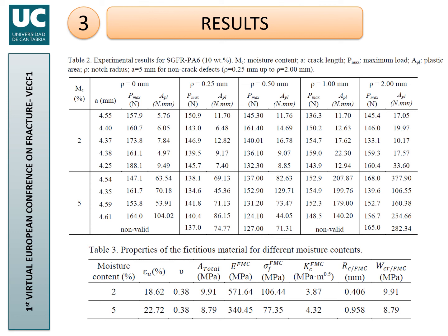So with all this, we just have to compare the average strain energy density introduced on the defect tip, again, as I said before, provided by the Lazzarin and Berto formulation, with the capacity of the material to store this strain energy density, which is given by the last column on the table below.